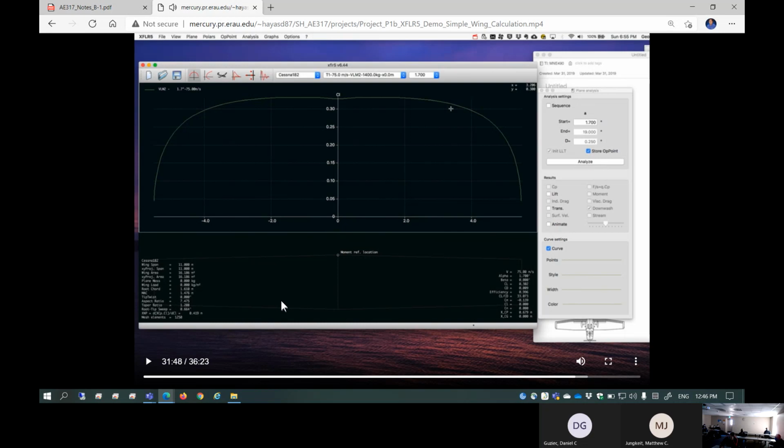Now, one thing you have to notice is once you put the fuselage, you are going to have a dip here. Okay. So you're going to see that dip. It is also going to negatively affect the span efficiency factor. So you have to design everything based on the balance. If you put a huge fuselage, like a manned airplane, you can't avoid having a dip in the center position here. Okay. And also, this distribution is going to be affected by a range of Reynolds numbers too. You can compute all of those things.